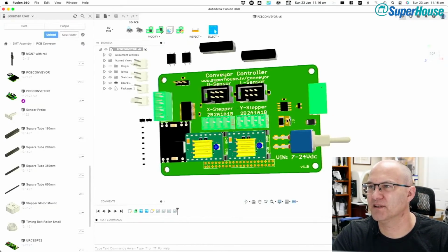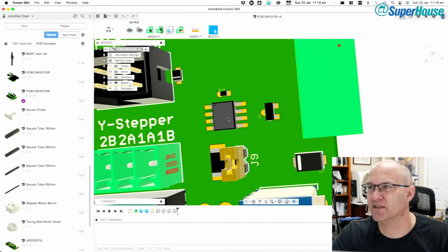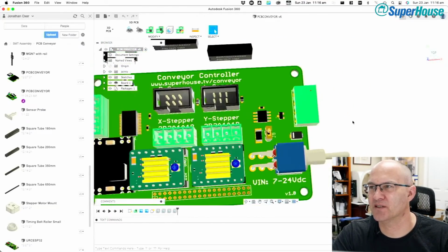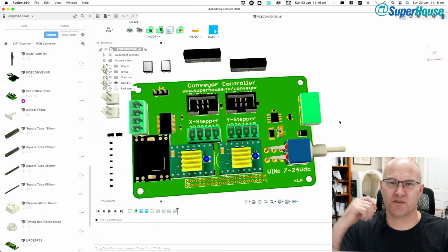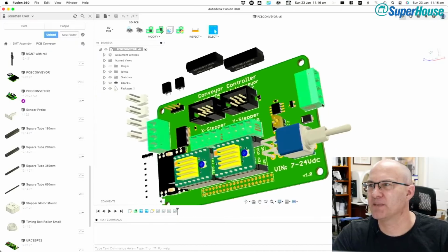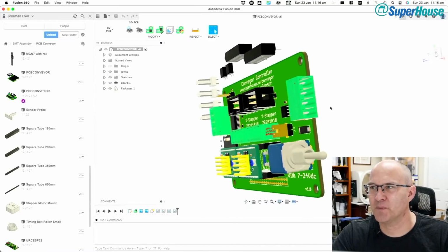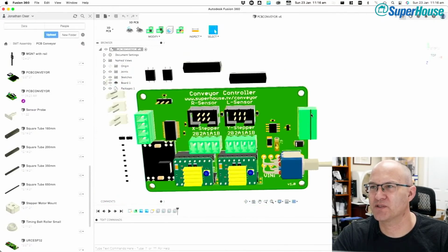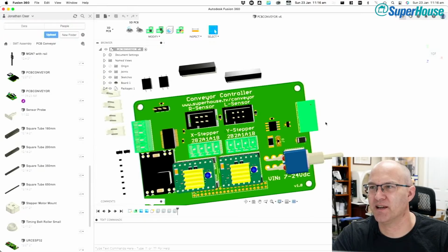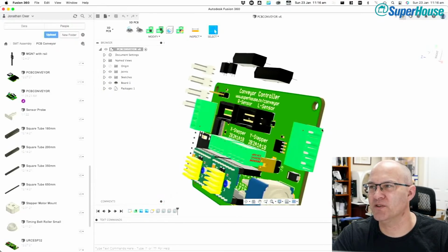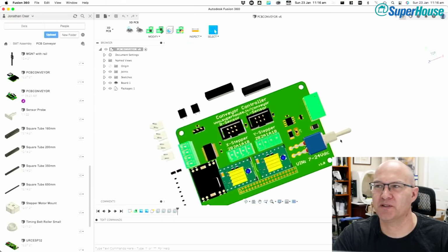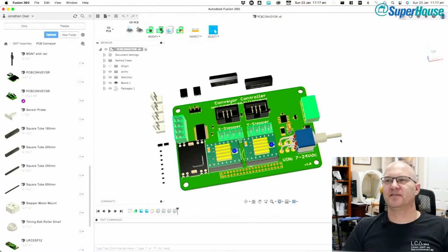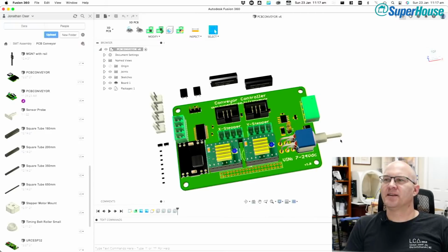Now, oh yeah, so what have we got here? CAN bus on here, and that's the termination selection for the CAN bus. I thought about putting this on an external termination resistor that is on a connector, and you plug it into the thing. So I should explain. These four-way headers are for power and CAN bus. So it would typically be plus 12 volts or 24 volts and ground, and then CAN high and CAN low. And if you wanted to, you could just plug in a two-way terminal block and just supply power to it. You don't need to use CAN bus if you don't want to.